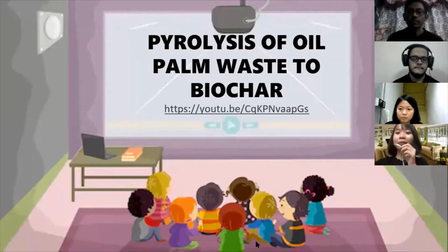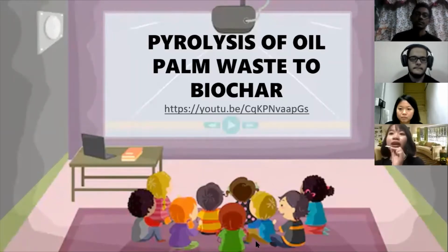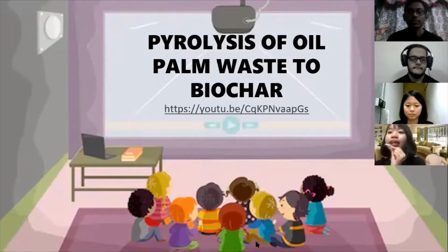Hi guys, I'm Hui Ling. So I will present on the pyrolysis of oil palm waste to biochar. One of the best ways to reduce the oil palm waste problem is by converting the oil palm waste to biochar through the process of pyrolysis. The pyrolysis process is conducted by heating the oil palm waste to a very high temperature in the absence of oxygen, producing the biochar along with syngas and bio-oils. Before we move to the next slide, let's watch a video on the pyrolysis process.